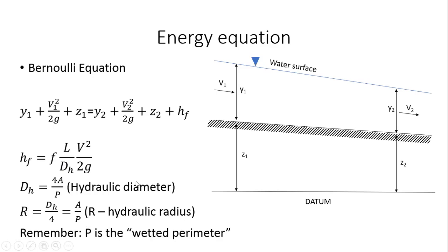Okay. So now, one of the interesting things about open channel flow is that we can use what is called the uniform flow approximation to understand a variety of different situations, right? We can assume that the flow is uniform and solve a lot of practical problems, right? So now when I say uniform flow, what I mean is, as we already discussed, that the flow parameters are not changing as a function of space, right? Which means that the flow depth or the flow rate, of course, it's steady. The flow depth, the flow velocity, these are not changing as a function of space.